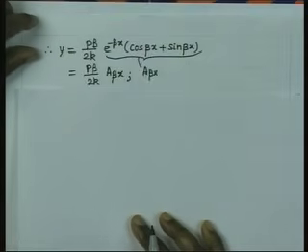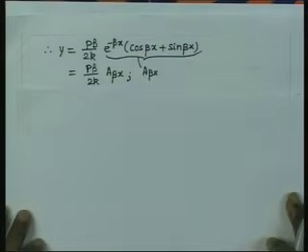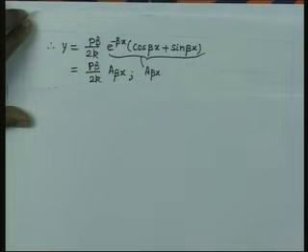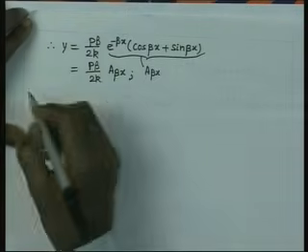Once you have got that deflection, you can calculate the slope, bending moment and shear force at every cross section. Obviously, when you are interested in calculating the stresses due to bending moment, you must have the value for bending moment. So it is worthwhile to see how the expressions for bending moment and shear force at a particular section can be obtained. So, we will do that.